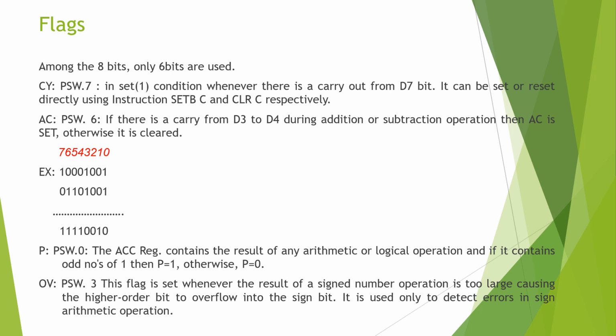So this is the addition operation, and if this is my result, from this result section we can also say that as there is no carry generated due to addition, after this addition operation the carry flag is obviously in the reset condition, that means the carry flag is cleared. Okay. So now the next one is your parity flag. If we consider the parity flag, it is not PSW0.